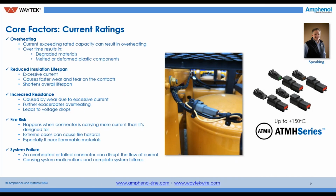Continuing on, core factors or current ratings. Considerations are going to include overheating, with current exceeding the rated capacity of the connector. Over time, it's going to degrade the materials. It's going to even melt or deform the plastic components of the connector. Reduced insulation lifespan: excessive current causes faster wear and tear on the contact and shortens overall lifespan. So it's important to have quality insulation, combined with making sure that we have the right temperature rating on the connector for the application and the environment that it's going to be in.